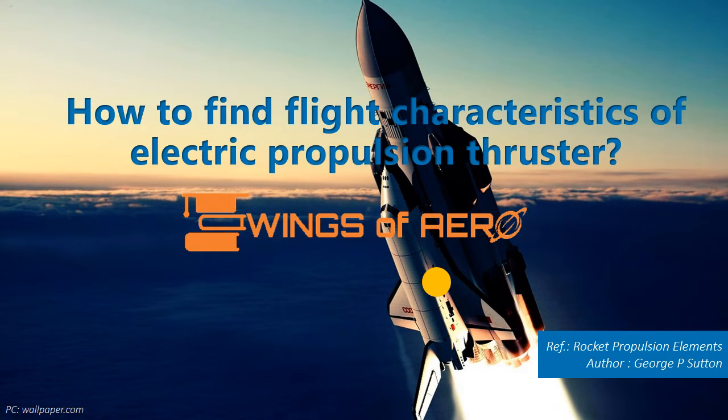Consider an electric propulsion thruster. Determine the flight characteristics of an electric propulsion thruster for raising a low satellite orbit. The following typical values are given. Specific impulse is equal to 2000 seconds, thrust is 0.20 N, propulsive time 4 weeks, and payload mass is equal to 100 kg. Specific power of the power plant is 100 watt per kilogram and thruster efficiency is equal to 0.5.